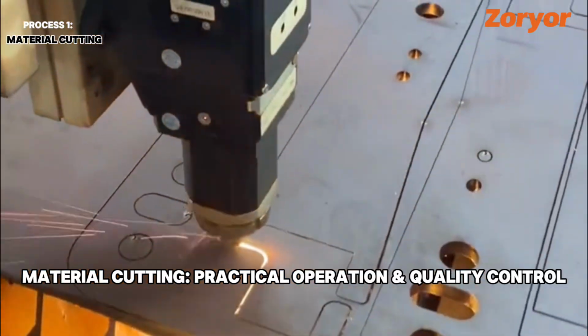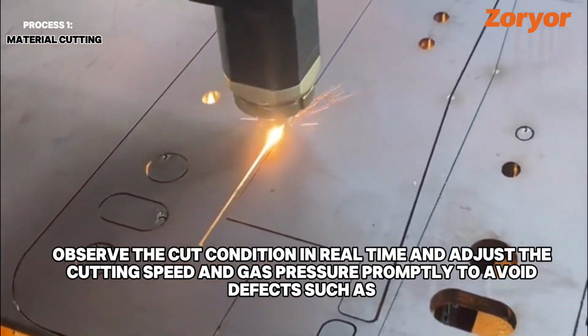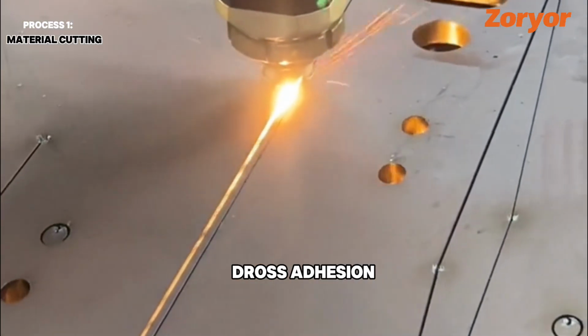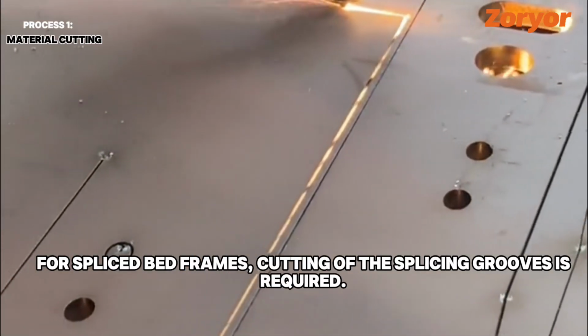Material cutting, practical operation, and quality control. During the cutting process, observe the cut condition in real time and adjust the cutting speed and gas pressure promptly to avoid defects such as cut deflection, dross adhesion, and cracks. For spliced bed frames, cutting of the splicing grooves is required.